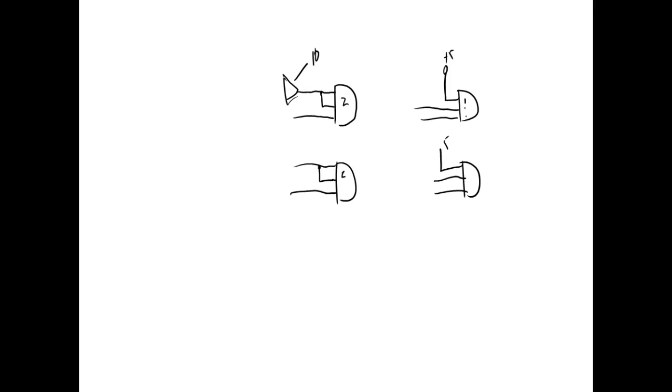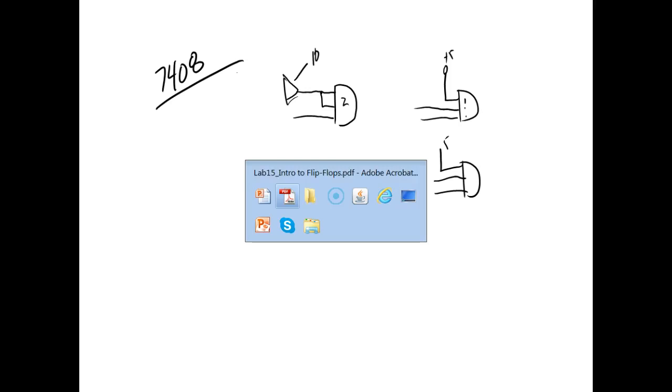So I shifted over, even though the lab doesn't call for it, so I wouldn't have to do stuff like that. I shifted over to a 7408. What's a 7408? Look that up in the front of your data book. So it's a 2-input AND gate. So this is the guy we're using. So let me tell you what pins I used. I've already wired it up for y'all.